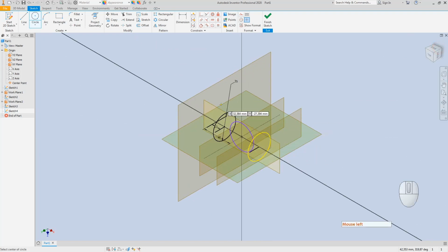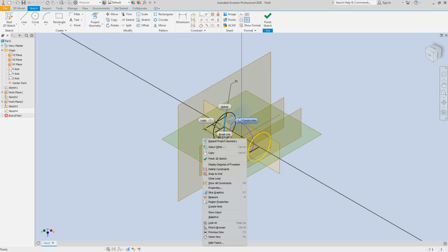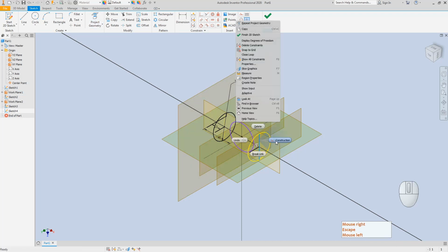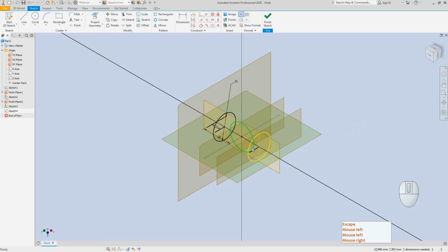Okay, I will just create a new pathways. The first thing I need, for the loft process, is the pathways between these two. The first thing I'm going to do is create on the XZ plane by starting a new sketch to have the 55mm between this circle and this circle. Let's start this example. Again, I will just change my view.